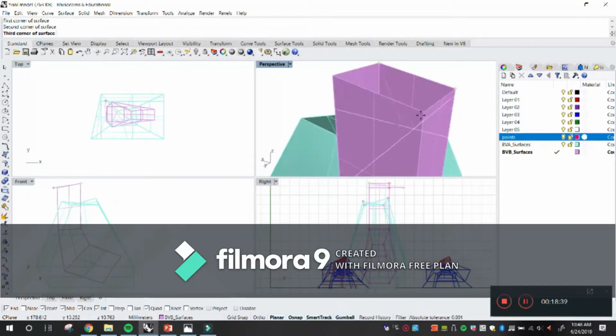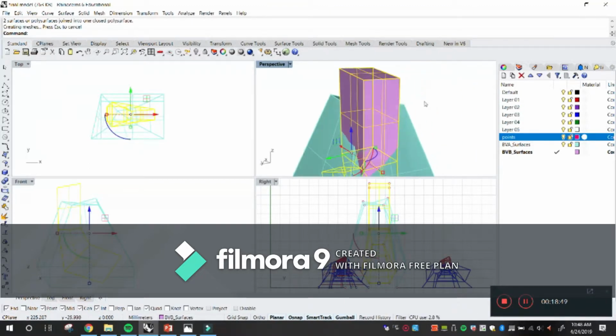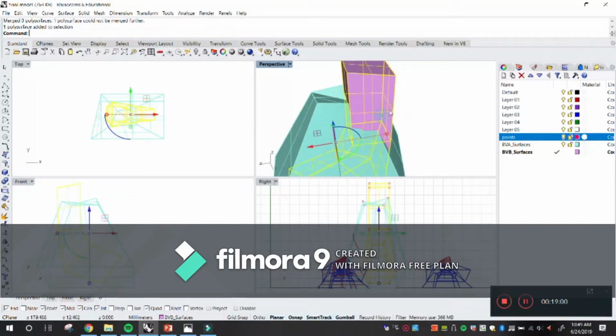Oh no, the layer is correct. Okay, and if that happens, these are already polished surfaces. I can just add it to it, right? But again, join. Right. Okay, it's always good practice to just type merge all faces. It just connects them. Right now, it doesn't make a big difference, but later on, I'll show you guys what it does, or I can point it out.